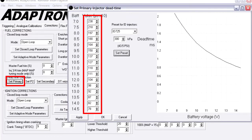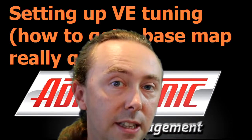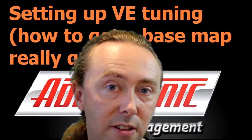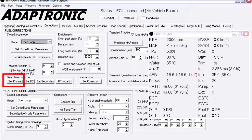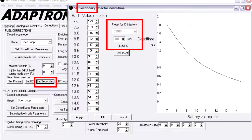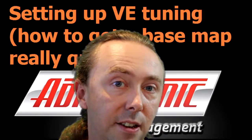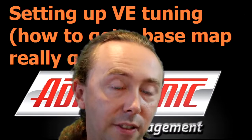If you're using staged injection, then the injector type has to be set to dead time and flow. You can still use the Injector Dynamics characterization built in the software by going to the set primary dead time, set secondary dead time settings, selecting the injector type that you're using, entering the fuel pressure, and then the software will set up the dead times and the injector flow rate based on what you've set. Otherwise, you have to enter the dead times manually and the injector flow rate manually as well.